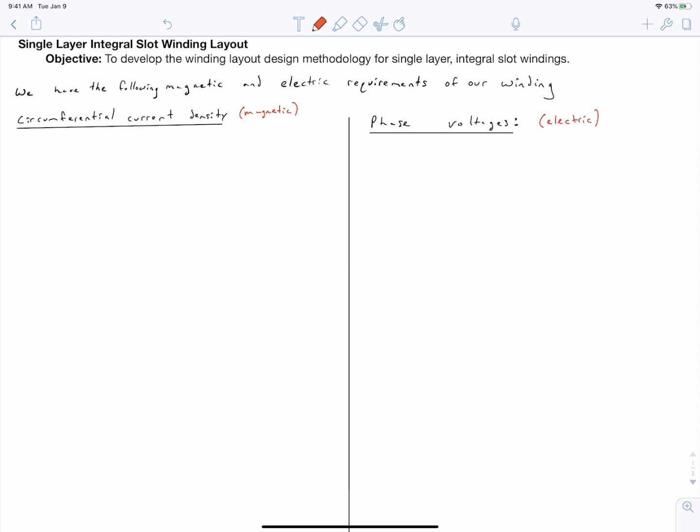And so we've talked about how the circumferential current density can be expressed as a Fourier series. And those Fourier series components we derive from the current linkage when we study a winding. And all of our expectations on this in terms of creating torque were on the fundamental quantity. That is the harmonic ν equals 1. We expected our circumferential current density to have the following form for our fundamental harmonic. And these expressions that I've written down here show how we want our circumferential current density to distribute itself on the inner bore of our stator.